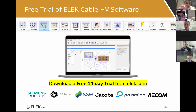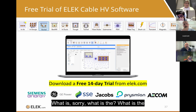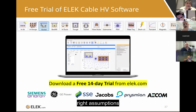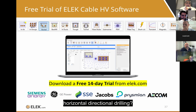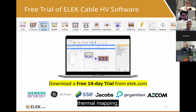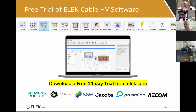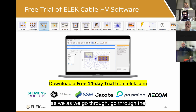How do we determine, or what is the right assumption for thermal resistivity when we use HDDs? And can we consider seasonal variations? What is the right assumption for the thermal resistivity values when we use horizontal directional drilling? Something with conformal mapping, I think. In the case of HDDs, you would cross many layers as you go through the layers of soil, so there might be different thermal resistivity.